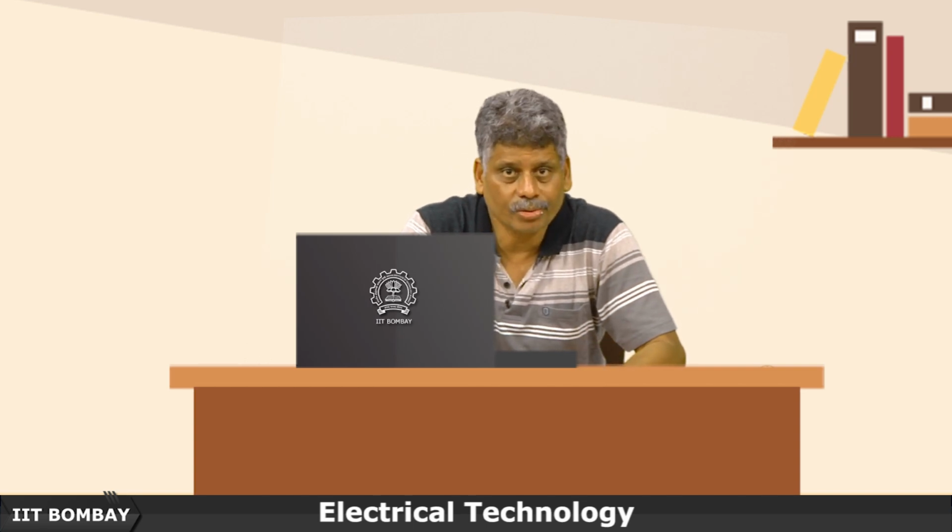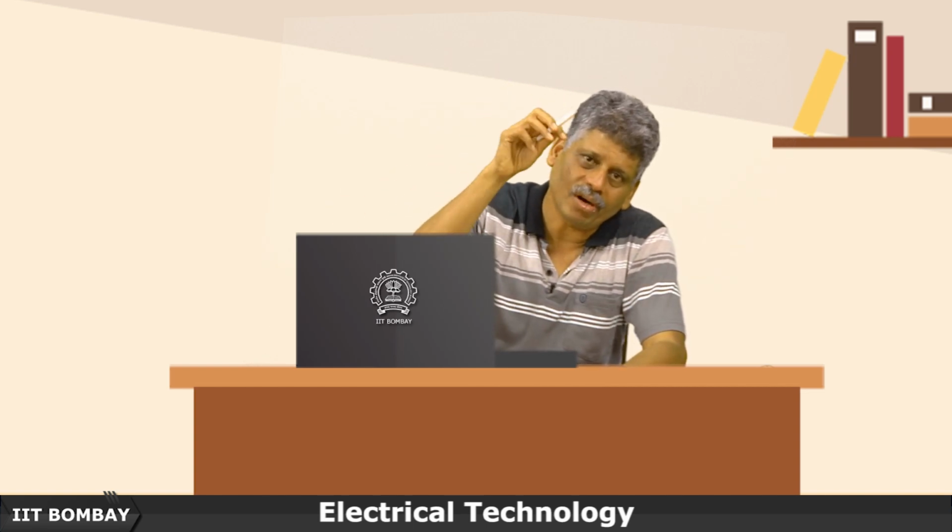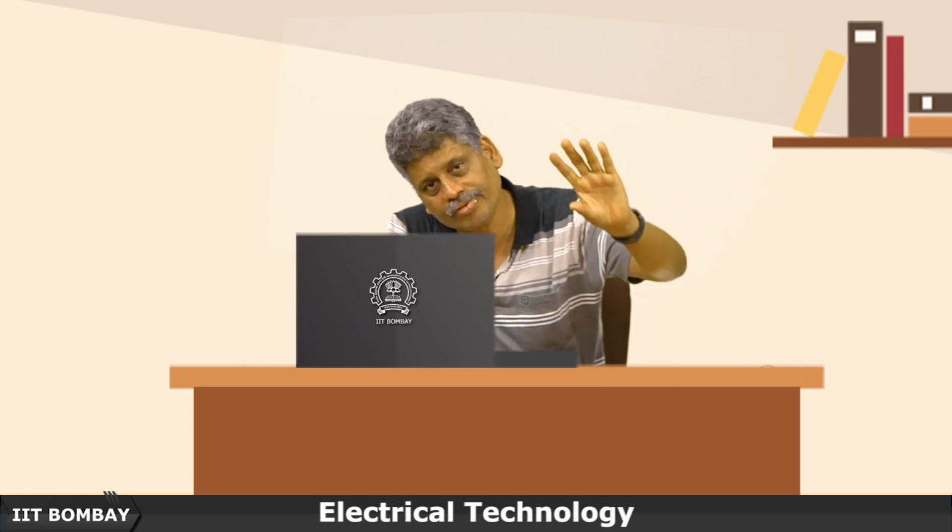So, the point is those instrument transformers, which we have not gone into, but I am just mentioning, is that we want fidelity in the reproduction of the waveform as is happening in the AC system. Because when there is a fault there will be transients and distortions, we want those distortions also to be captured properly. So, those are built towards fidelity, while what we have discussed mainly in this course is power transformers.